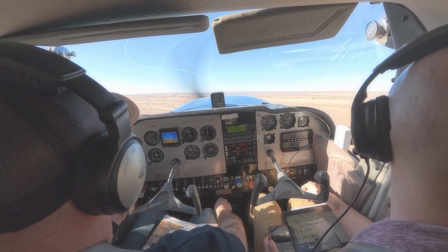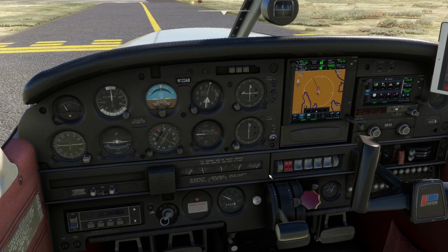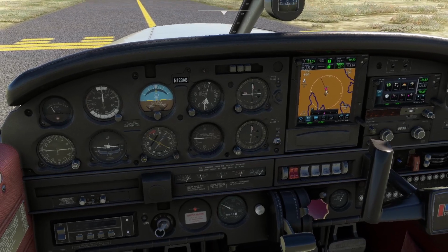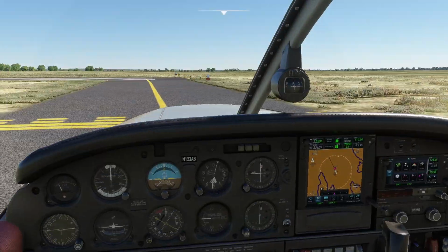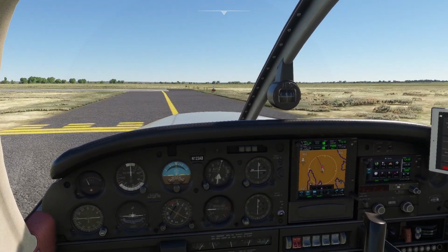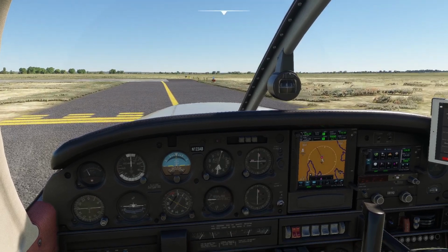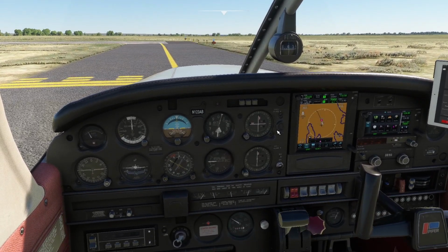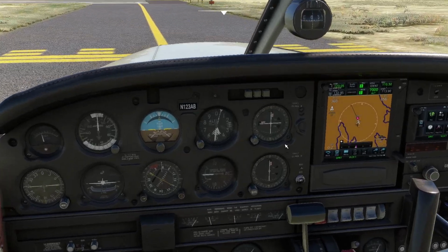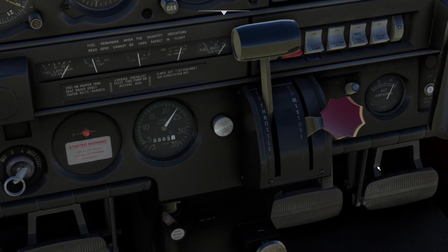Before we go into detail about constant speed propellers, it is good to review some operating characteristics of fixed pitch propellers. On a fixed pitch propellered airplane, as the name implies, the propeller pitch is fixed. The blade angle doesn't change. When the airplane is stationary, the propeller is at its greatest angle of attack. At full power, the drag created by the propeller significantly prevents us from reaching the maximum RPM on our tachometer.